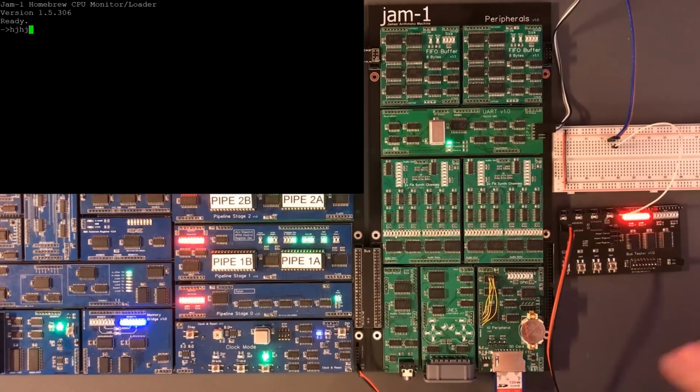So somewhere between the hardware and the terminal emulator, the characters I type in are being held back, waiting for the signal that it's clear to send. Let's get the test program back in. Now it is going to be difficult to outpace what the UART can do just using the keyboard, but I think I can do it just by running my hand down the keyboard. So switch back to trace mode and I will try and do exactly the same thing again.